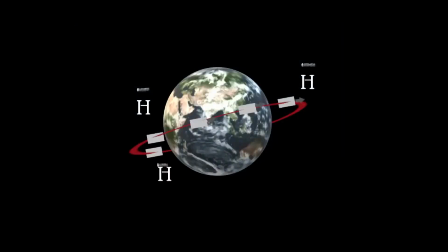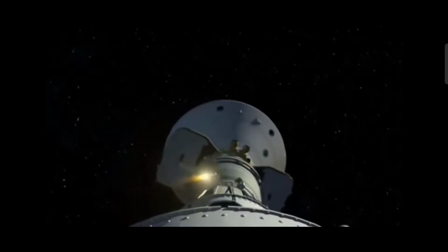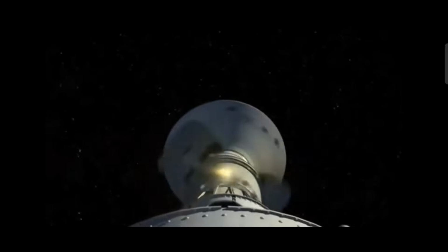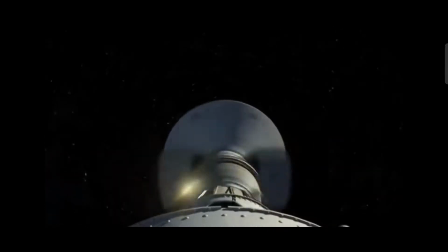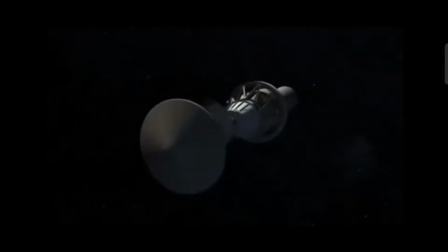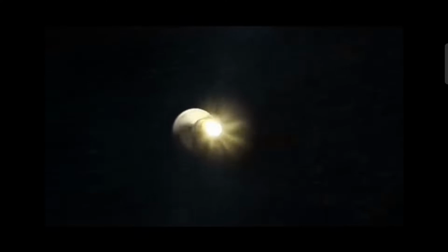Spin stabilization is useful to point in the same inertial direction, but it is not for pointing the angular momentum vector at Earth. For that reason, it's mostly used during spacecraft deployment when the gyroscopic stiffness is useful to maintain orientation until the spacecraft is free from the launch vehicle. To avoid these limitations, we can use a dual spin system.